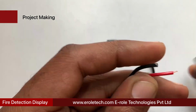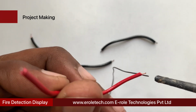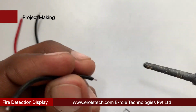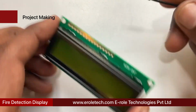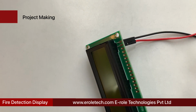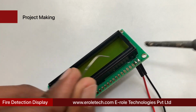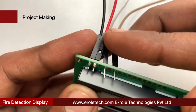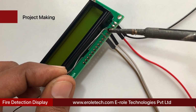We will take 3 wires, 1 red, and 2 black. We will use these wires later. Now we will solder a black wire at hole number 1, and red wire at hole number 2 of LCD display. Now we will solder a white wire at hole number 4, and brown wire at hole number 6 of LCD display.